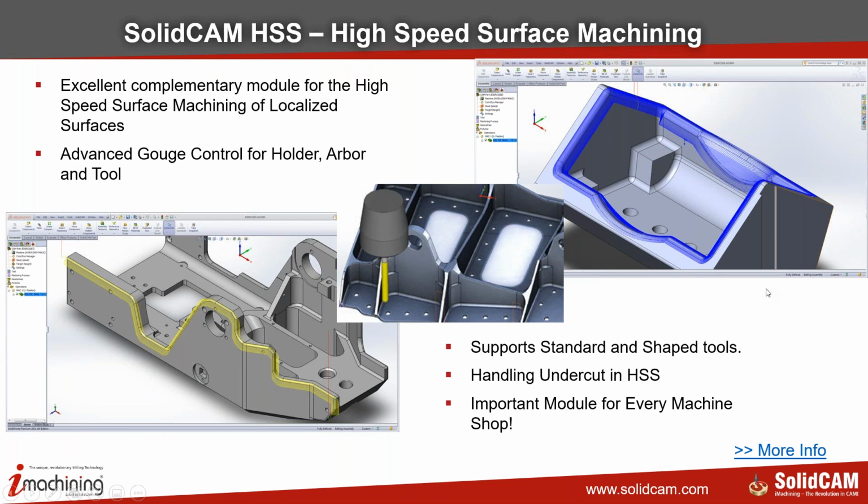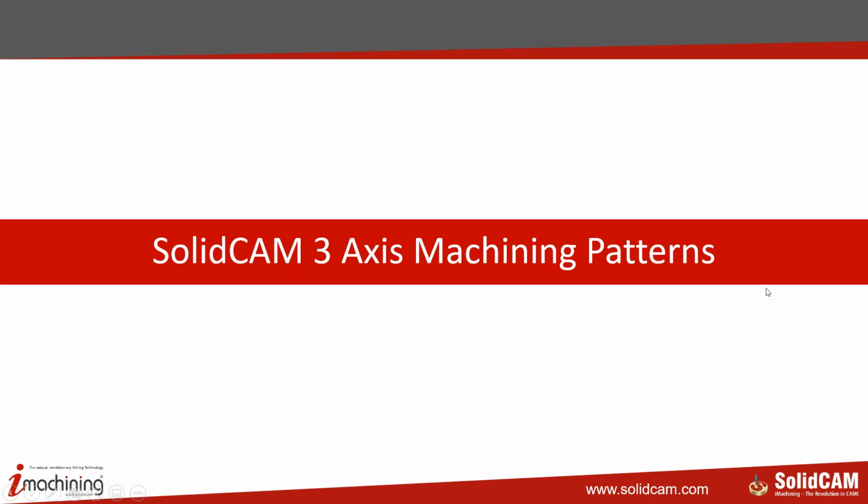When we go to HSM's 3-axis machining patterns, I explained to you that we have got tons of different machining patterns, but we used only the linear, the constant Z, and to some extent constant step over and rest machining. But there are several other possibilities within the generic HSM of SolidCAM. Some we used, some we did not. Even in constant Z, we have got several methods.